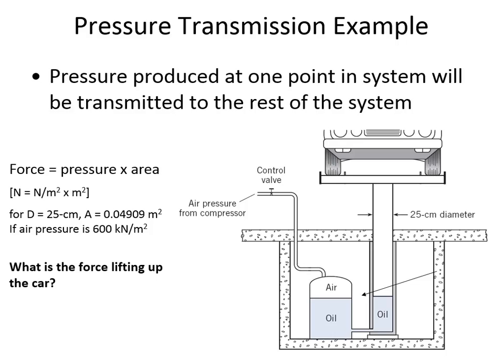So if we put in more air, that makes the pressure higher. So I'm going to make these lines longer just to indicate that the pressure is higher. And so what that does is it causes the cylinder to rise. So maybe now the cylinder would be up here, and this is all oil. The weight doesn't change, right? The weight of the car and the weight of that steel cylinder, that's not affected by how much air we put in there. And so W is going to be the same.